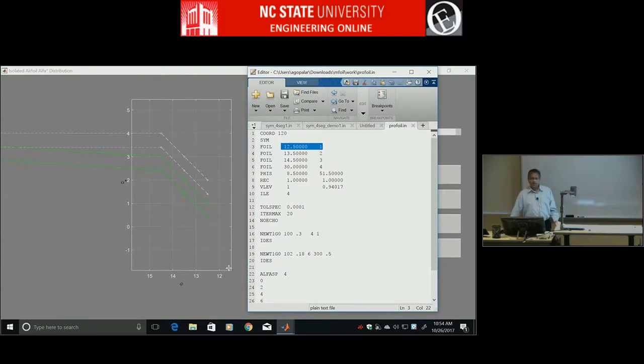That's because on the upper surface, phi increases towards the leading edge. I've purposely written this interface so that on the upper surface, phi will be plotted in reverse. So you can always think of this as the leading edge, this as the trailing edge, just like how we draw the airfoil. This is the first segment, second segment, third segment, and then you go towards the leading edge. So this is 12.5, 1.